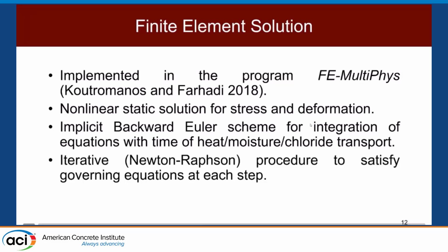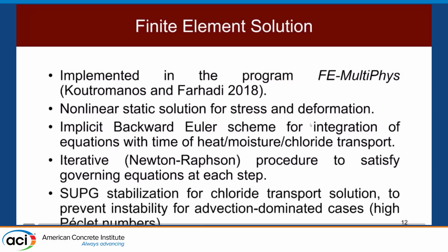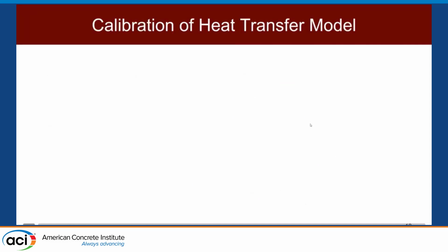And we also employ an iterative, specifically a Newton-Raphson procedure to satisfy the governing equations at each step of our time marching analysis. One other note is we also employ SUPG streamline upwind Petrov-Galerkin stabilization for the chloride transport solution to prevent so-called spatial instabilities which may occur for advection-dominated cases, or if you prefer, for situations involving high Péclet numbers. Now I'm going to quickly glance through the calibration process.